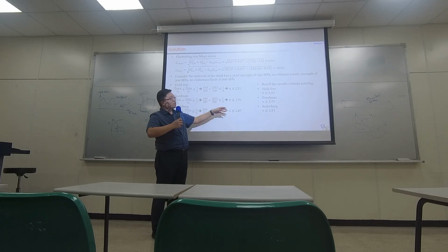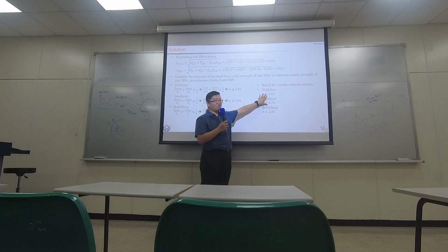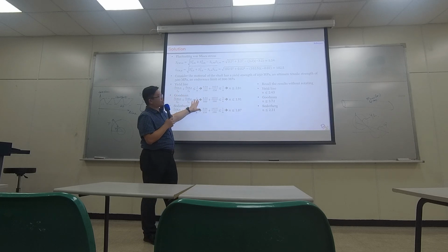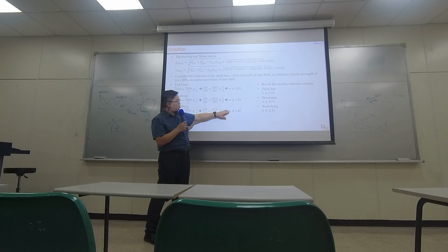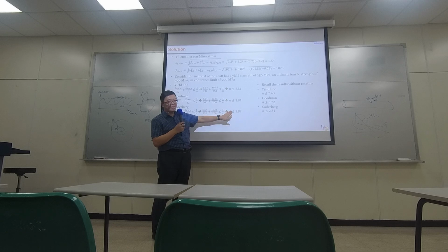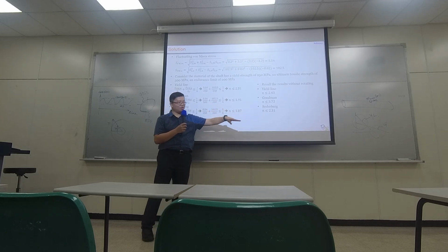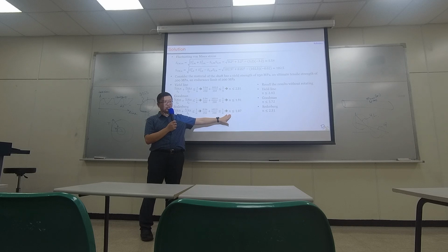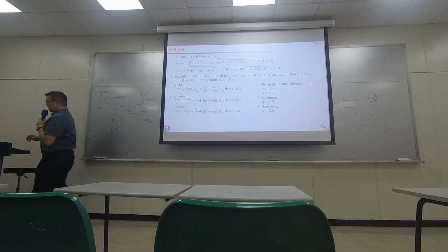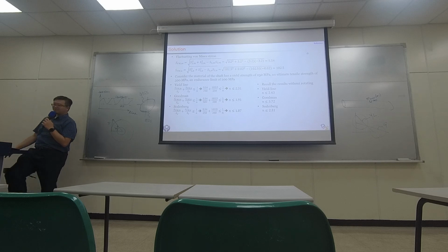Okay? So when the shaft is not rotating, all models are safer. But when the shaft is rotating in this particular problem, all models are giving us lower safety because of this fluctuating stress. Just like what happened in the previous problem, Soderberg is the most conservative one, but this time Goodman is the second most conservative one. Yielding line is the least conservative one.